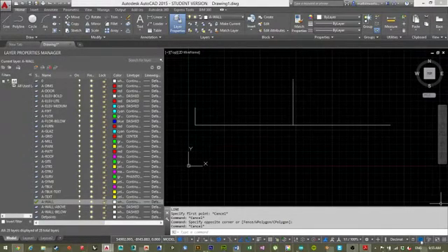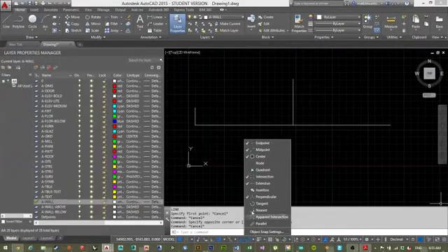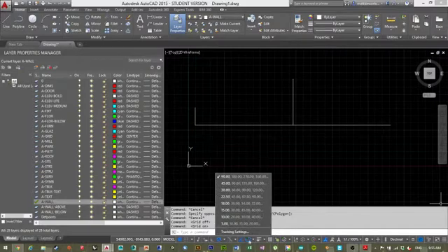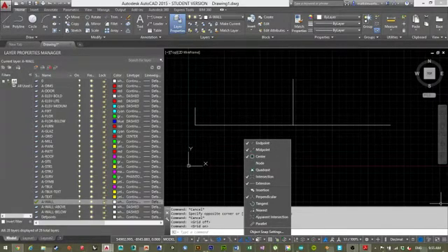And then these other ones, those ones don't really matter. So really, the most important ones down here are this box here. You used to be able to turn these all into words instead of icons in 2014, and they took that away, which made me mad, because the words made a lot more sense than all these little icons. But really, the grid, polar, and this kind of box here, which changes your snaps.